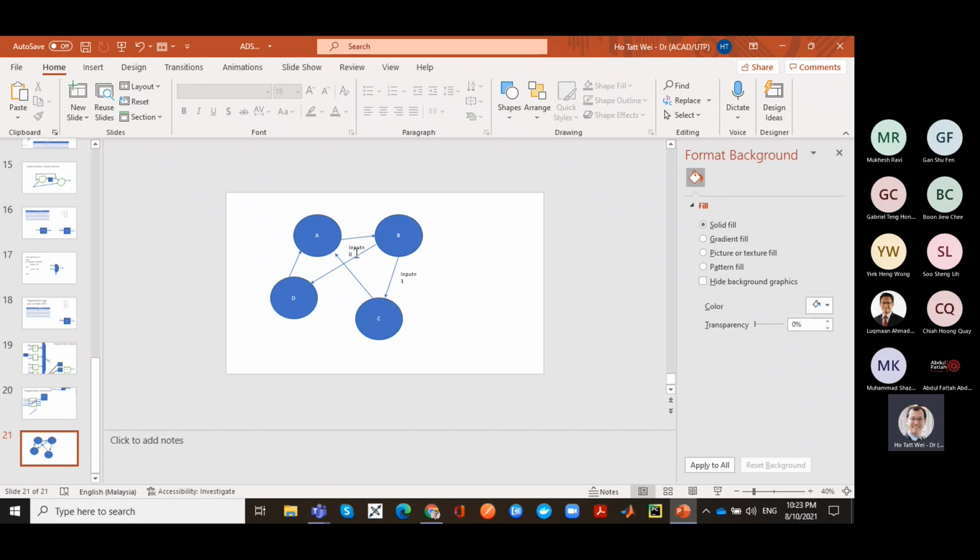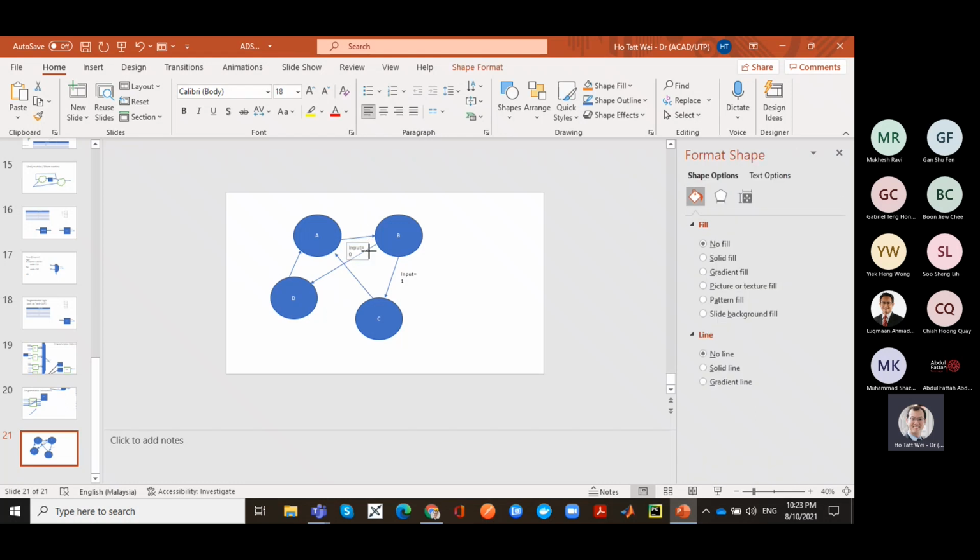Most people from undergraduate forget that if you don't label the state transition with an input, it will transition to the next state automatically at the clock edge. It's like saying I'm writing a program, but I'm not waiting for the results to compute. I'm just going to move from mode to mode to mode.